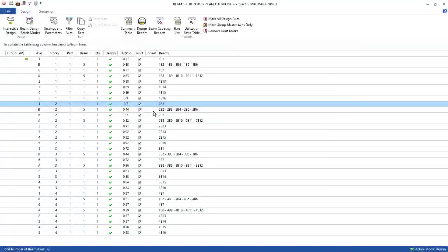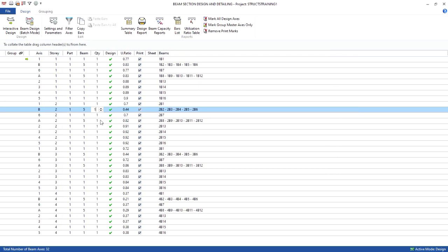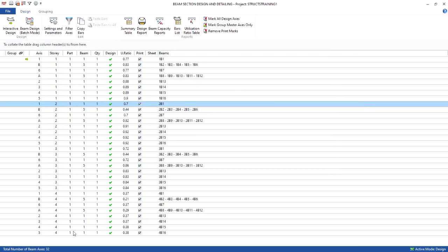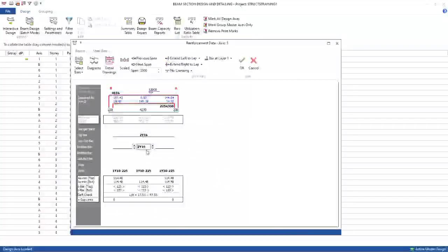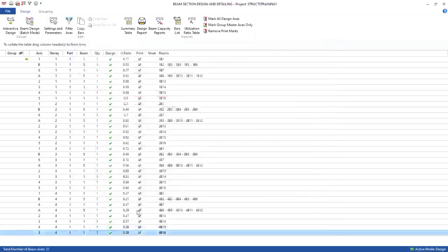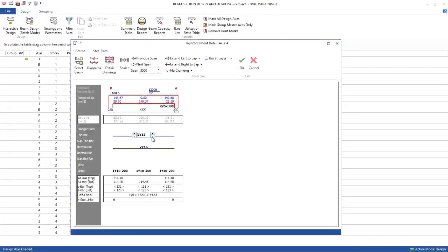Why I checked this for just the first floor is because it's a typical floor all through. First floor is the same as second floor and same as third floor. Only the fourth floor I'll come and check the beam because it's the roof beam. While you're detailing, you can extract the first floor detail and see typical floor details, and you're good to go. For the roof beams, 2Y16 top and bottom all through. Y12 can go. Where it's better, I'll put 3Y12 bottom, Y12 top.